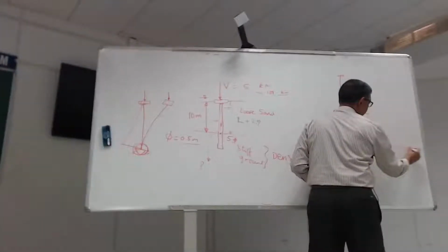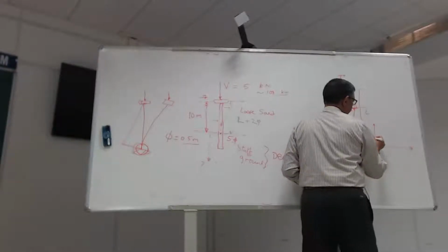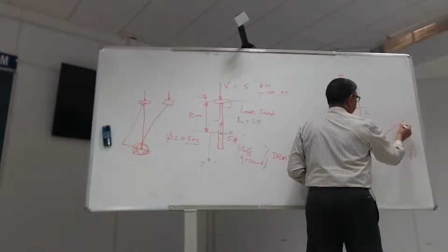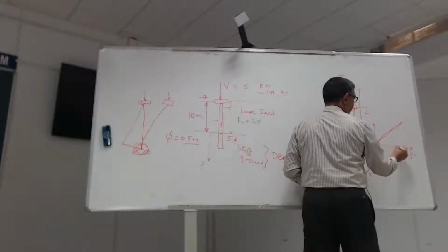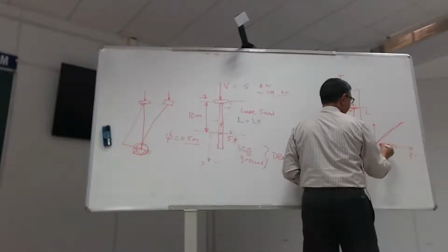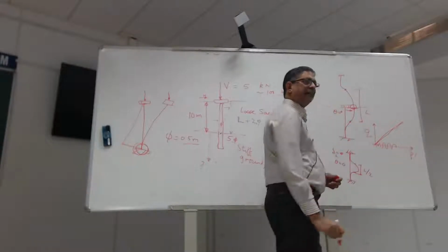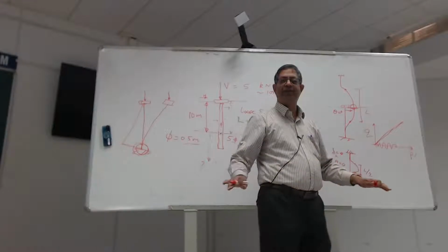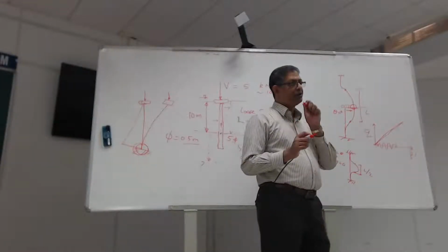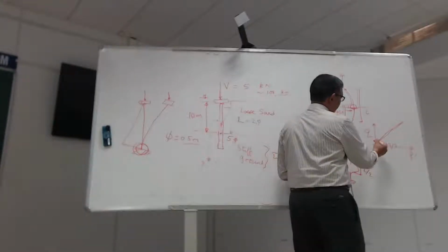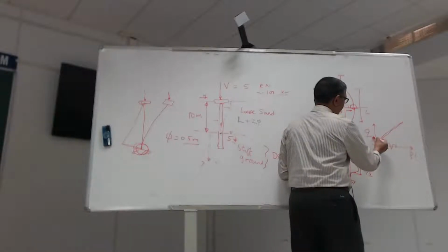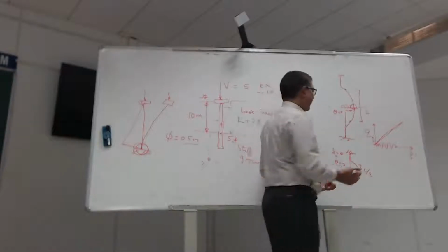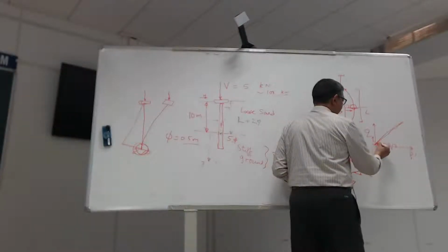If I'm plotting on q-p', that's my critical state line. I start, cycle down, and come to full liquefaction. So this is where my soil state is after the ground has liquefied. As the pile tries to apply shear stress, so we're asking it to do that, the only way the soil can respond to this is to say, right, I can't, I'm already here.